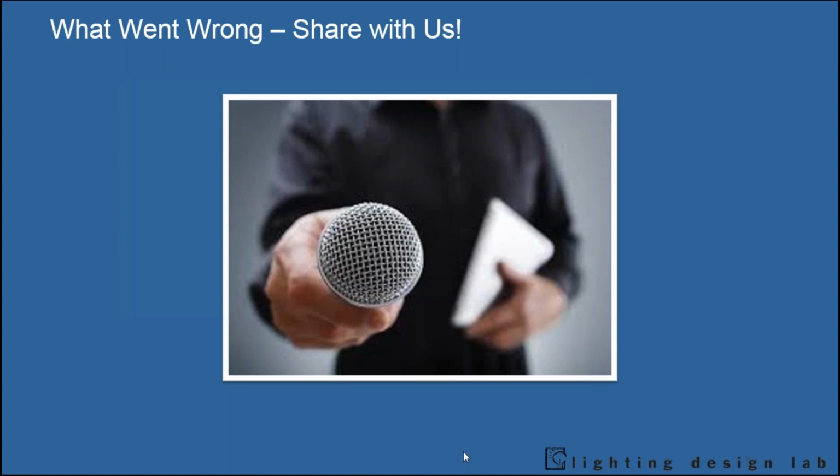And the occupancy sensor in that room is also controlling the HVAC for that room. So if someone enters, the lighting sensors say, hey, somebody's here. I'm going to bring it to just a lowest level setting so you can get across the room, do whatever you want. But it arms the HVAC system to know somebody might be coming in to use the room. So over a timeout period, it says, okay, it's been longer than 4 minutes, I'm going to kick the temperature up and start rewarming this room. So there's ways you can do that.